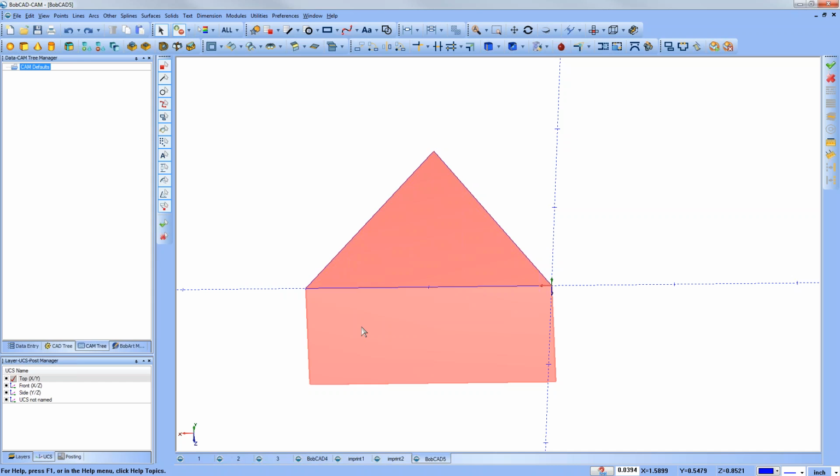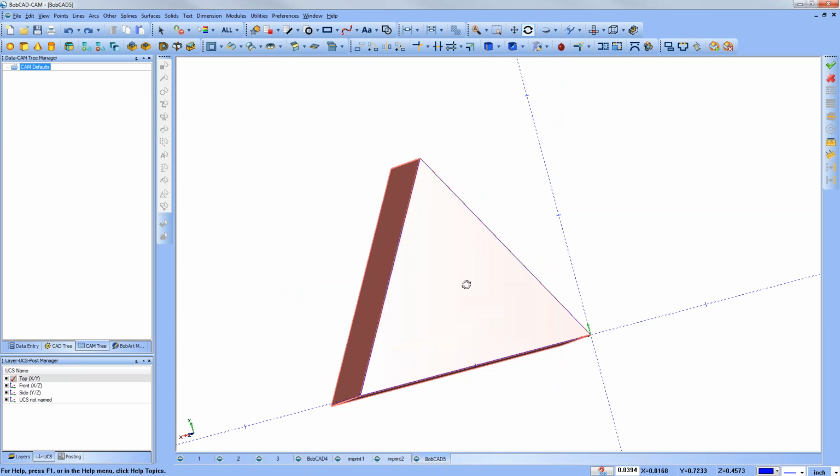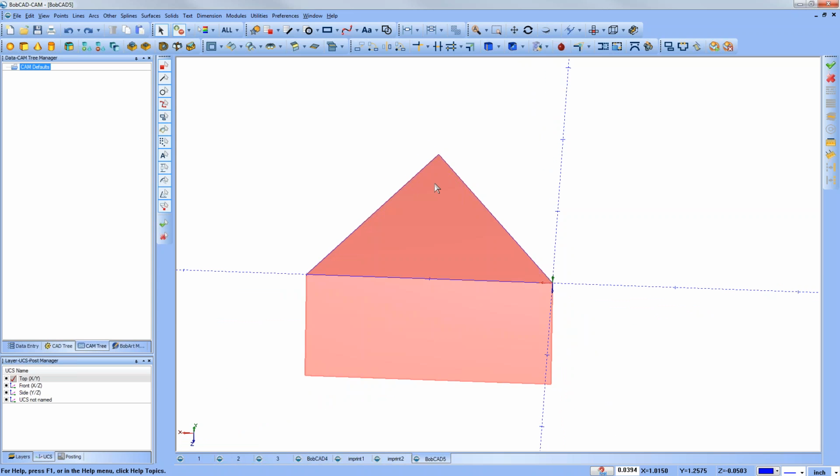similar to what the shell gave me, providing there were no fillets at the bottom. I can do it with a taper, where shell wouldn't handle a taper. So it's got to be a consistent wall thickness. I think there was a question on that. If it was a tapered shape, I would do an extrude cut from within this part.